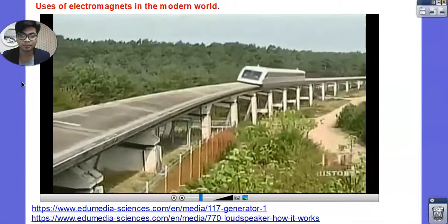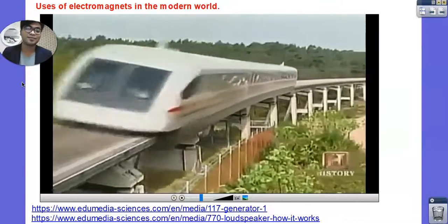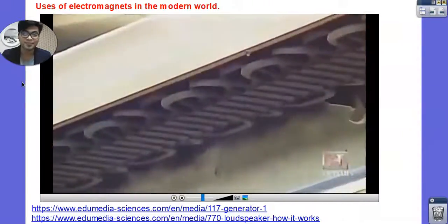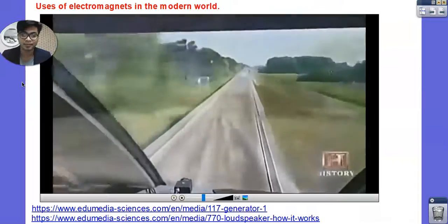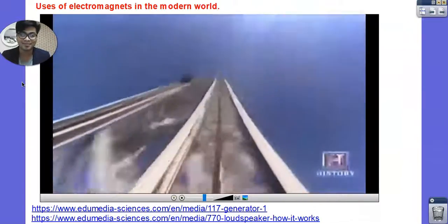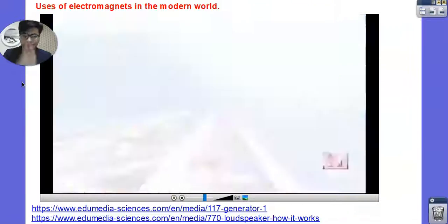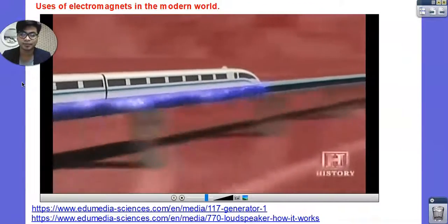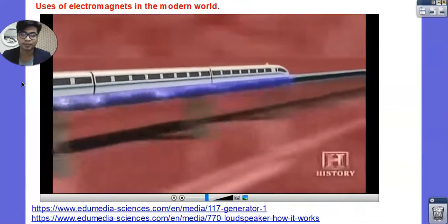If you're looking for the motor that propels the maglev forward, don't bother looking anywhere on the train. It's laid out flat along the guideway. A system of magnets, like that used on Magic Mountain's Superman roller coaster. This is, for example, another application of the linear synchronous motor. If you synchronize the changing of the poles with the motion of the train, you can keep the forces going.